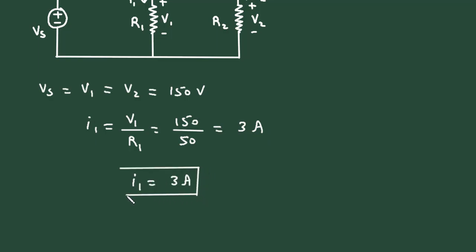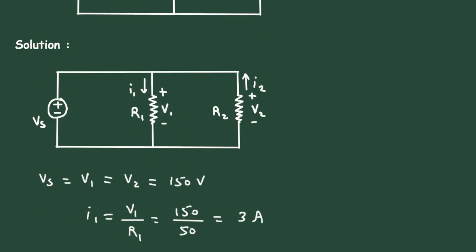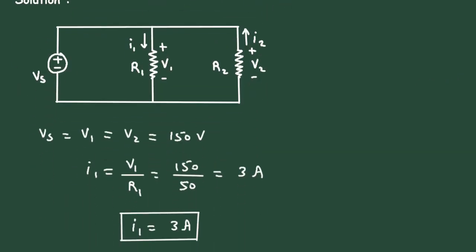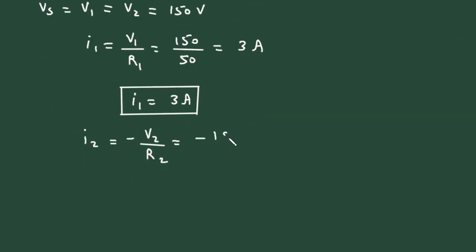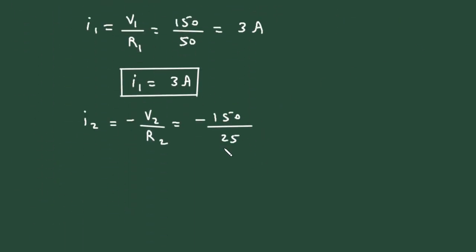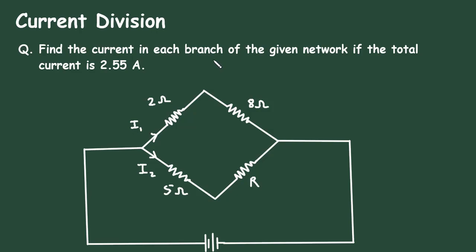Now if we substitute the value of IT, the value of IT is 10 ampere. So it will be 10 ampere multiplied by, now here R1 into R3. The value of R1 is 10 and here it is 20. So 10 into 20 divided by 10 plus 20, divided by R2. The value of R2 is 15 ohm. So 15 plus same, that is 10 into 20 divided by 10 plus 20.